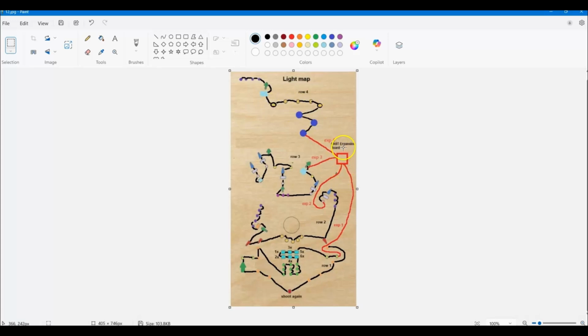And Fast has an expansion board that will manage the lights. So basically it has 4 different inputs for lights, and each input, I think it's 32, can handle 32 lights. So this one will have 4, like I mentioned. I'm using all 4. And some of them have 23 lights, some of them might have 30 lights on my setup, but I basically mapped it out. And when I actually start building the play field and lights being placed, those will help me map how my wires are going to be routed, and how they're going to be hooked up, because that's kind of important.